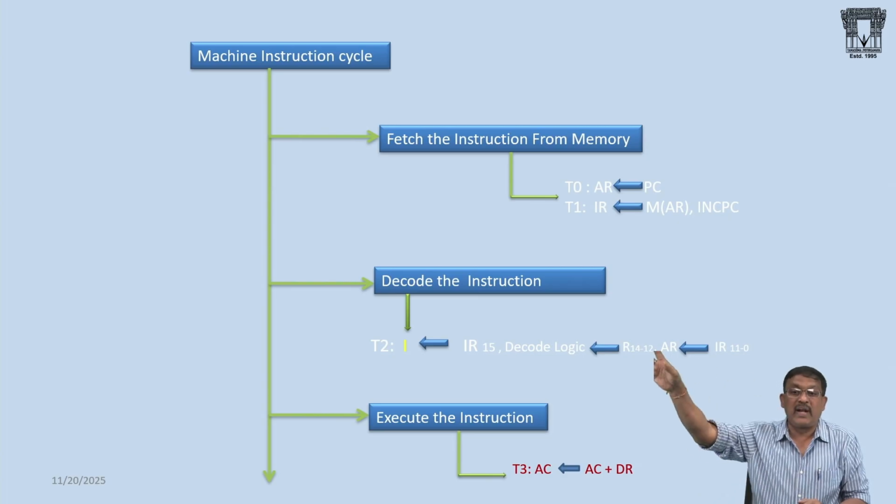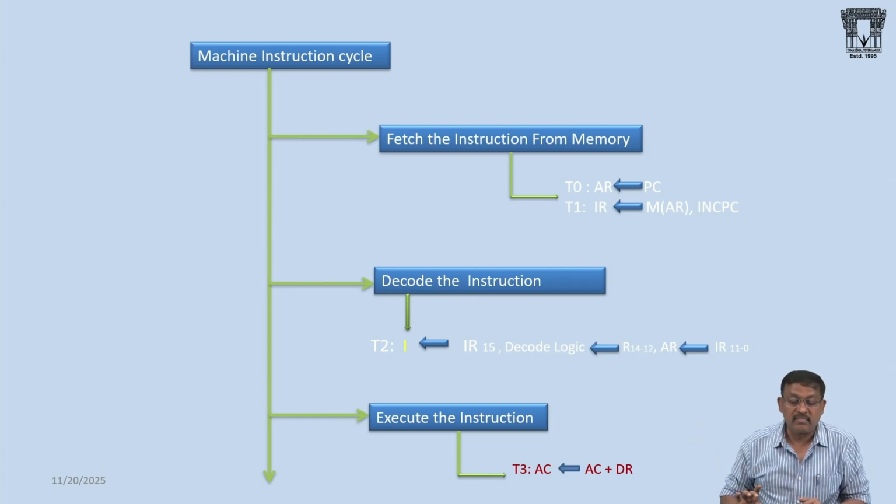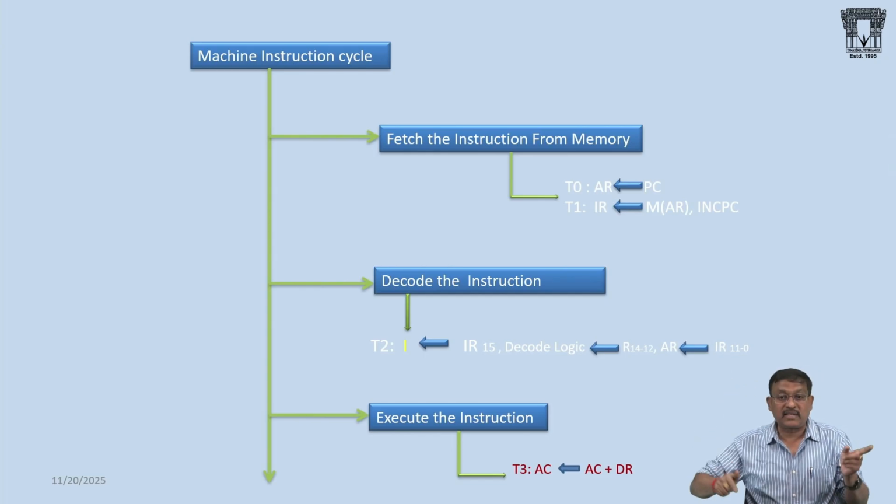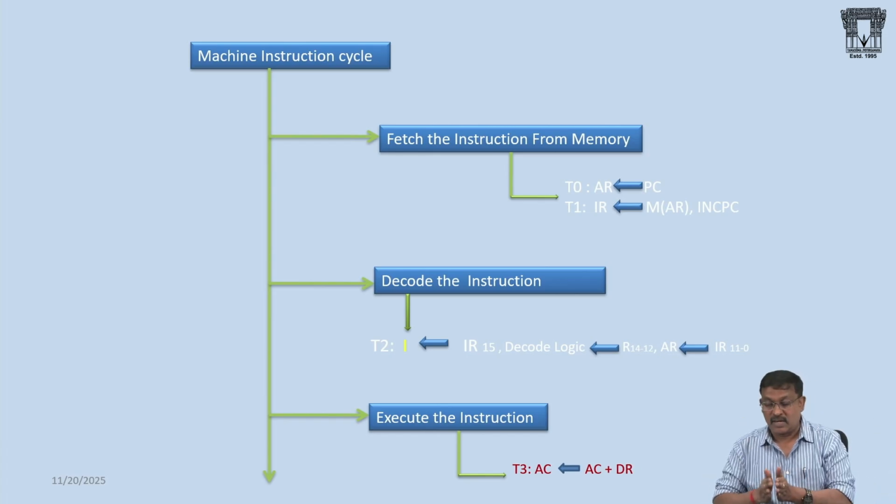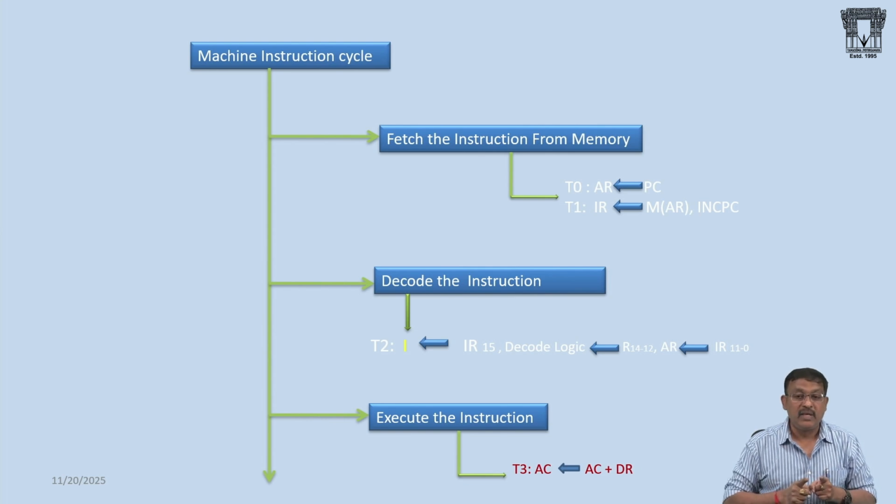This is the IO direct addressing mode of instruction. The mode of addressing is direct. The address of the peripheral device is represented within the instruction. Those are IO reference instructions. To access the output device and the input device, the accumulator is acting as an intermediate device between the input device, the processor and the output device. So the processor will not directly read the data from the devices.